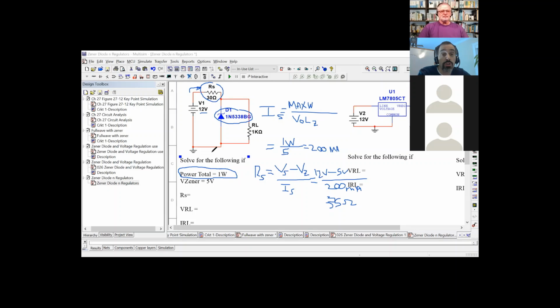Always make sure that your source voltage is larger than your Zener, but don't just change your Zener out and say, I want to give myself a 10-volt Zener, because you could destroy things down the pipe. I've seen that happen where people changed out the Zeners and forgot to look at the spec. They thought, well, I have one on the shelf, and it was a 15-volt Zener. And all you needed was a 3.6. You just cooked out a couple of comparators. So just keep that in mind. Okay, makes sense so far?